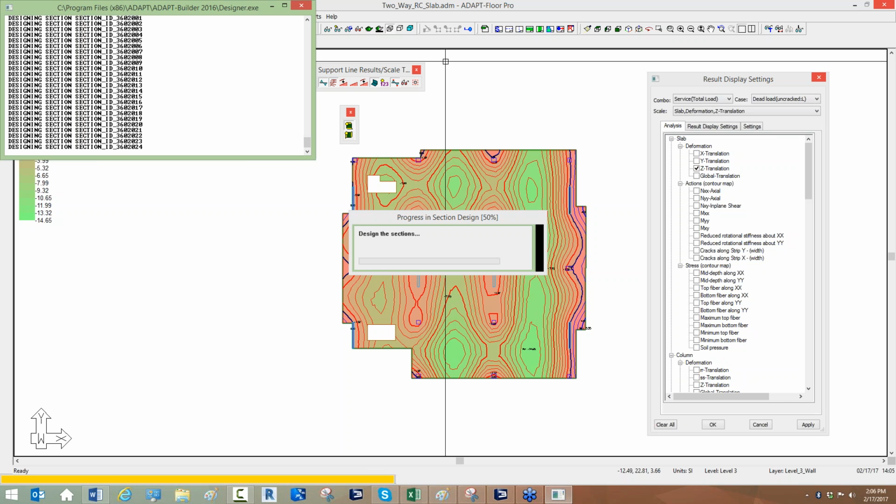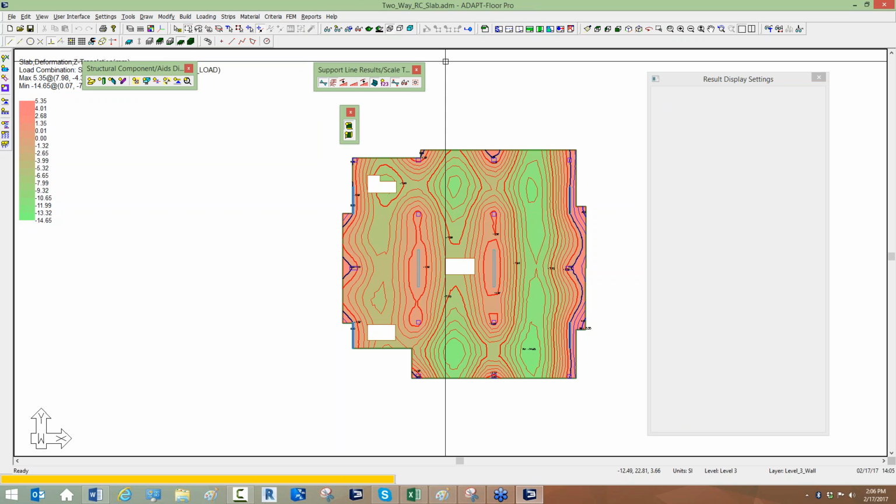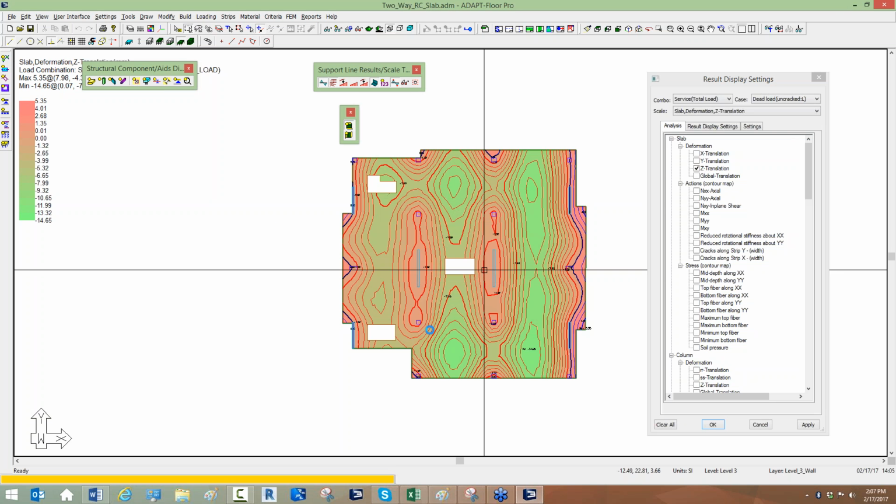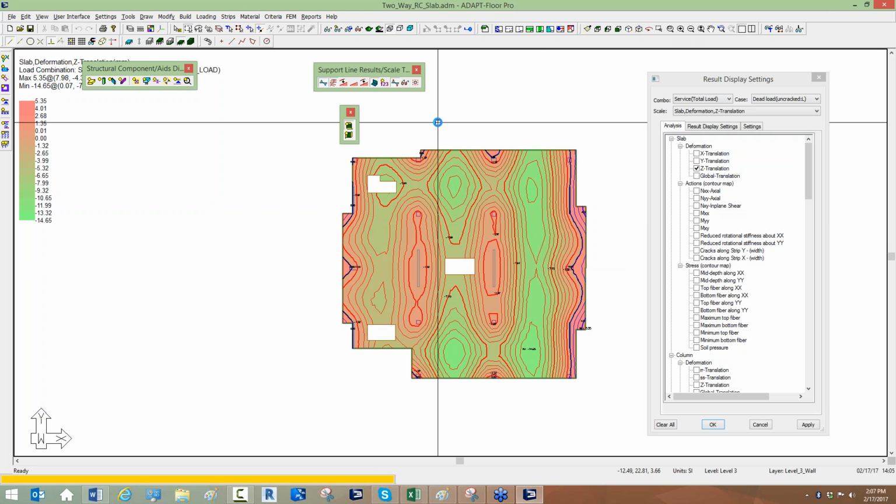And if any section requires either of those two items of rebar, service or strength, the program will then apply the spacing to that section. So if the output of rebar for service or strength, let's say, results in a maximum of 1,500 millimeter spacing over the width of a strip, the program says no, the spacing limit is 400, and it will actually add additional rebar to meet that spacing limit in the slab. And I'll give you an example of that now. We haven't done the crack deflection yet. That will be the last thing we look at.